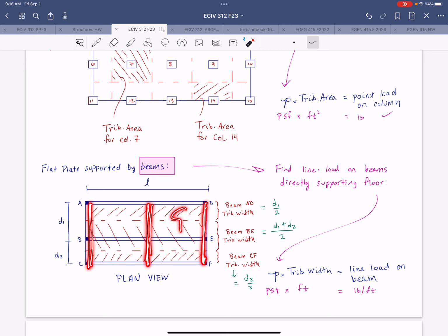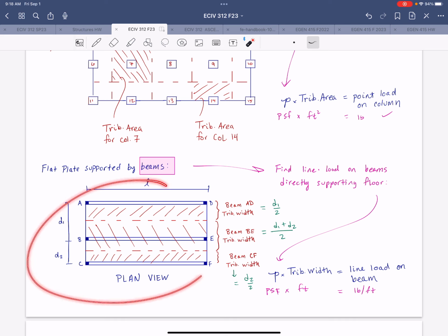If you had a concrete slab in between and you reinforced it in both directions, you could do it that way. But again, it depends on what that floor surface is, how that surface can transfer forces itself, and whether those beams in both directions are directly supporting the floor slab. So you could arrange for that to happen. But just based on this configuration, it should be pretty evident that it's a one-way floor system.